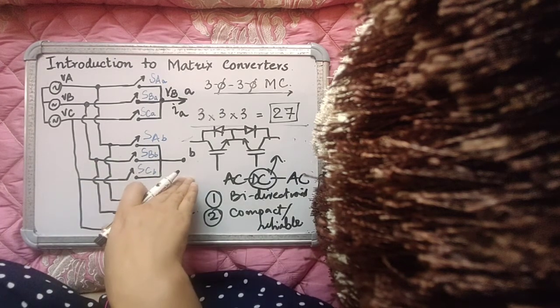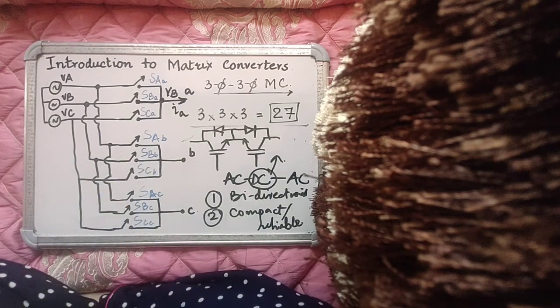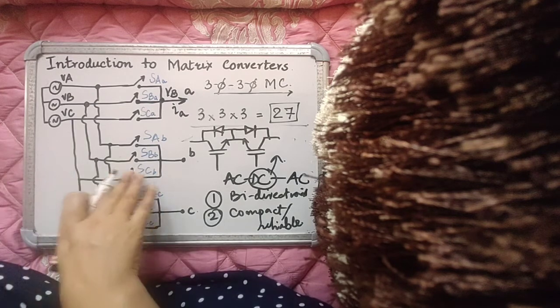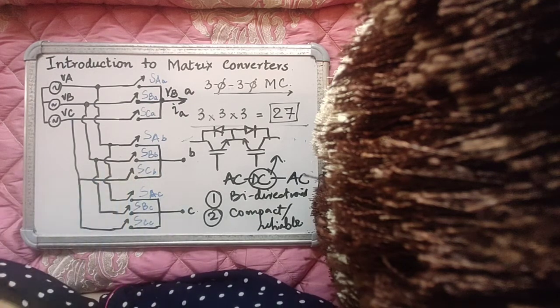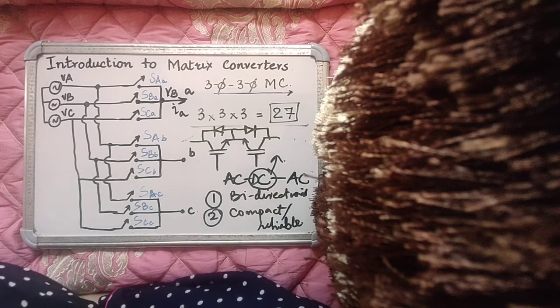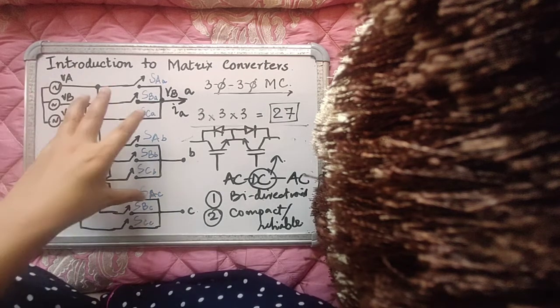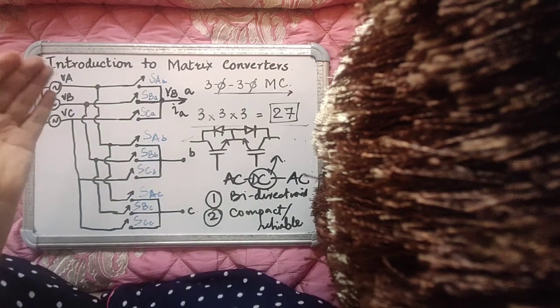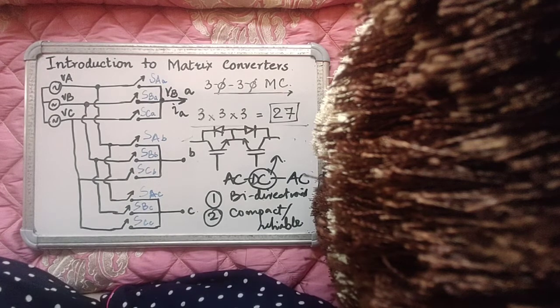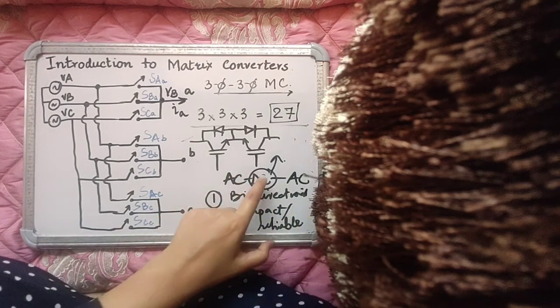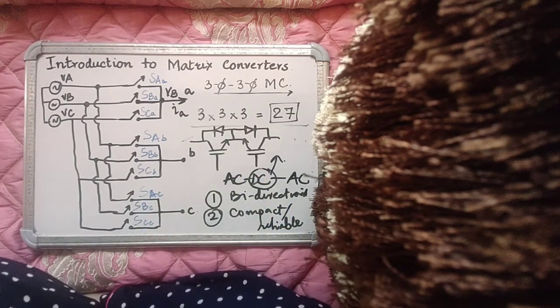In case of a matrix converter, because you do not have anything like an electrolytic capacitor, its reliability is higher, especially as power electronics device technology is improving. Matrix converters have more scope in the future because they are pure power electronics, or pure silicon solutions, as compared to AC-DC-AC converters, which also have some passive components.